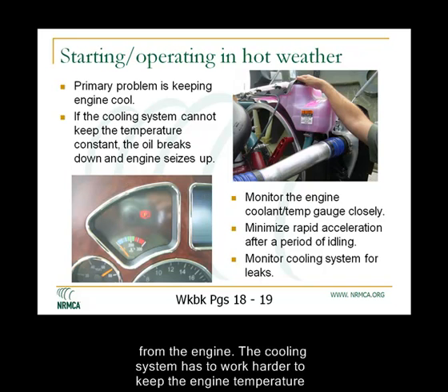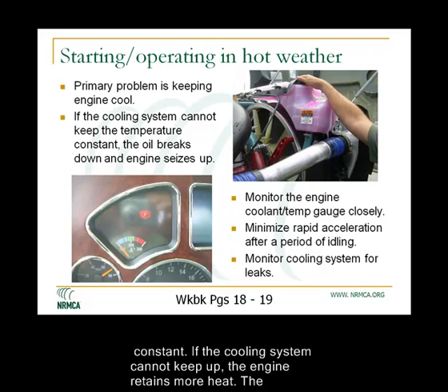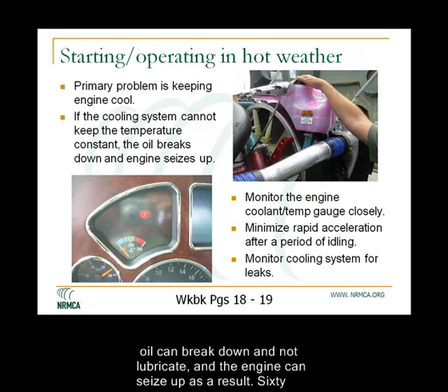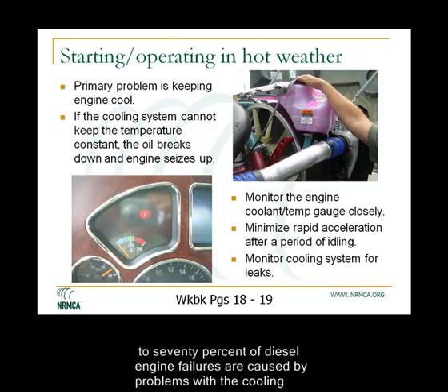If the cooling system cannot keep up, the engine retains more heat. The oil can break down and not lubricate, and the engine can seize up as a result. 60 to 70% of diesel engine failures are caused by problems with the cooling system.